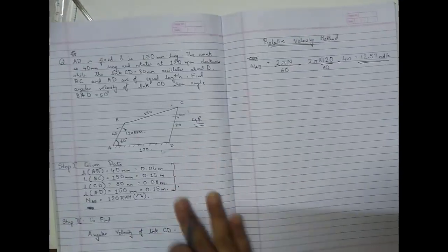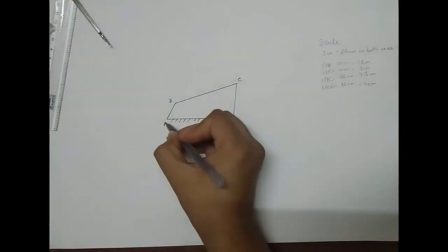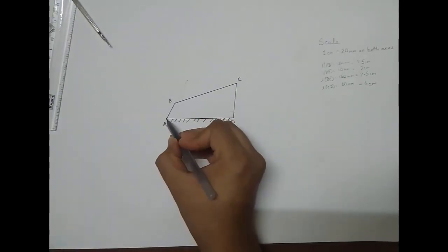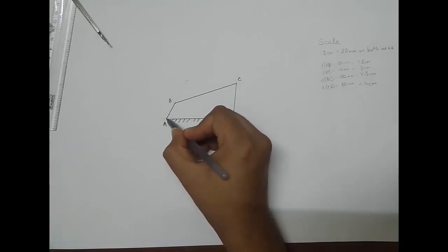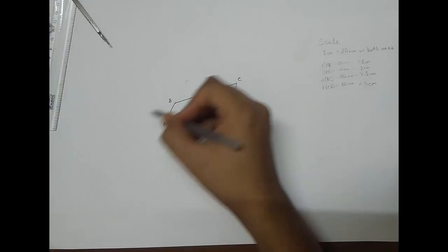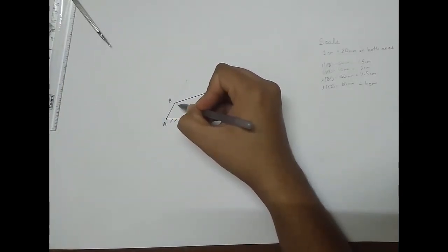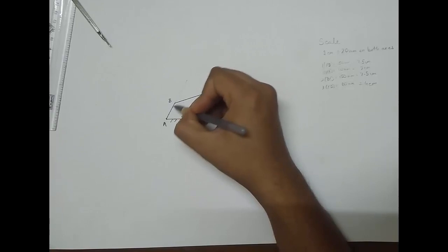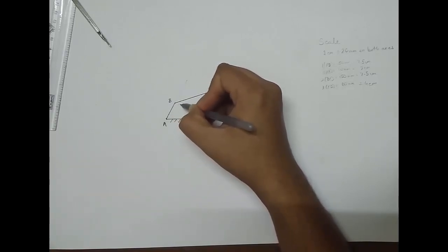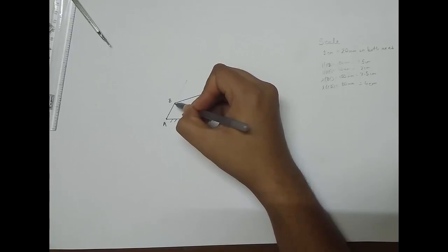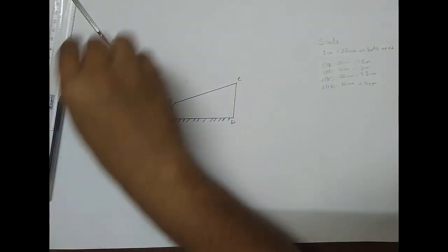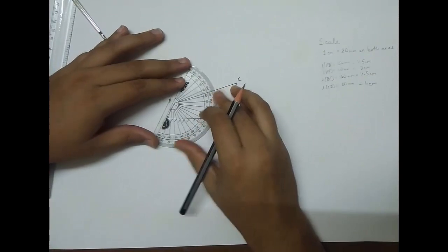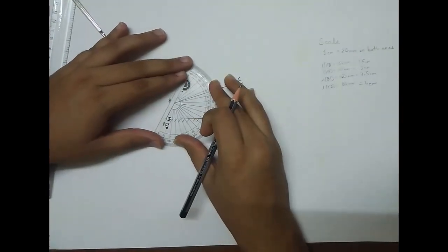Okay, now take a close look at this. In this mechanism, A is fixed. So link AB is going to perform pure rotation about this point. I have already taught you in the previous lecture that the velocity of point B will be perpendicular to link AB. This has been covered in my last lecture on relative velocity. So velocity of point B with respect to A will be perpendicular to link AB. Okay, so the velocity will be perpendicular to link AB at point B.